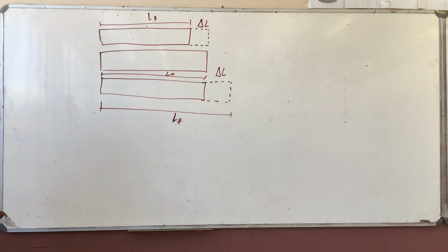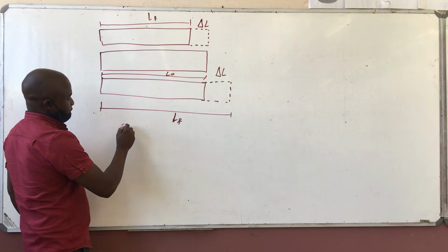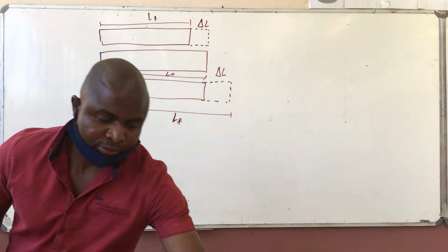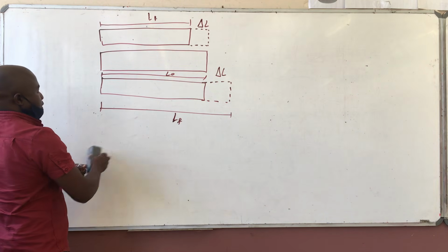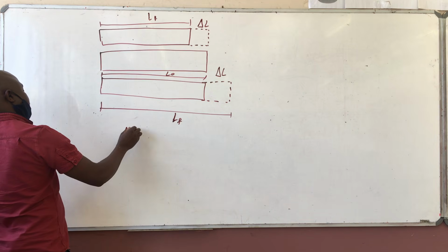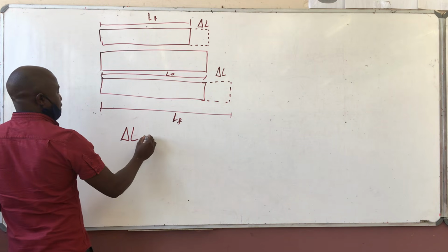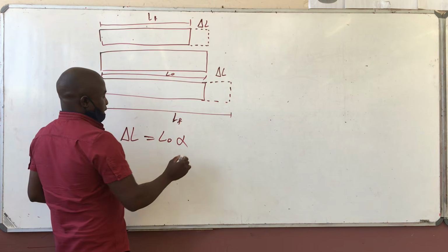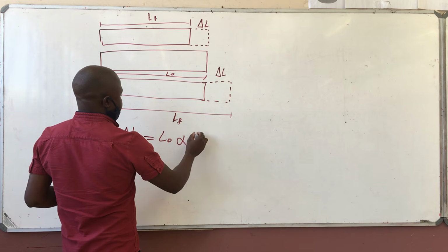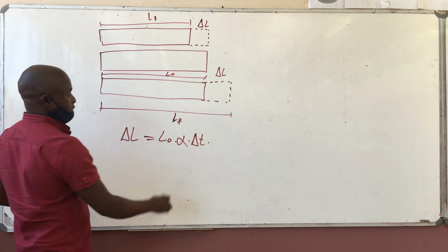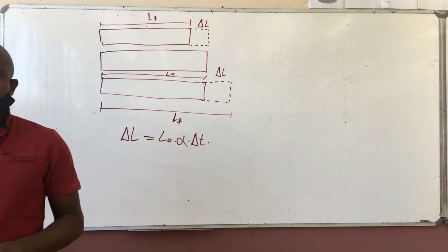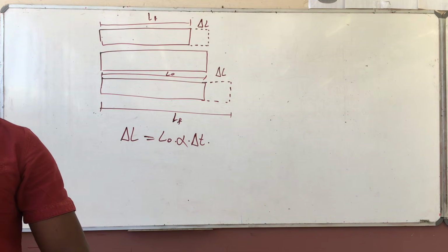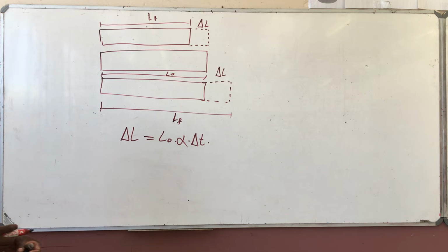So, your change in length due to temperature will be original length times coefficient of expansion times change in temperature. That will be your change in length if it expands freely without being under stress.